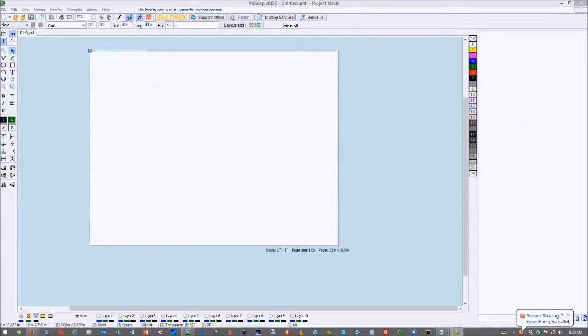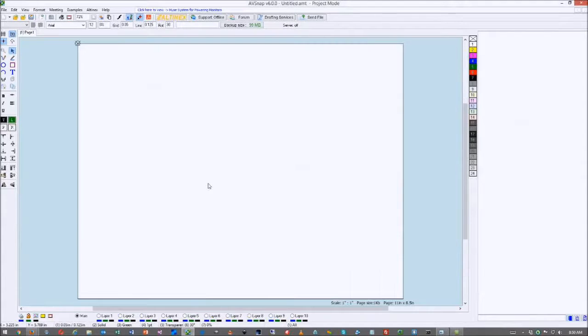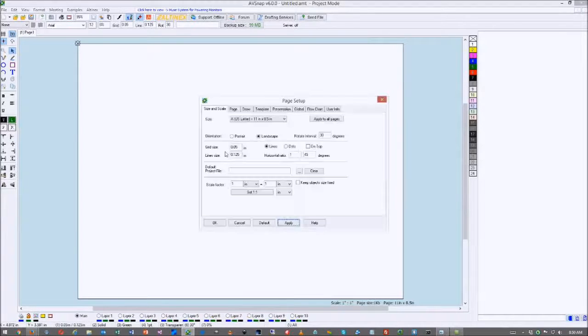But I do have a couple of questions in the chat, and one of the questions is about the plant picture JPEG. Yes, the plant picture JPEG, this will accept any type of bitmap. It could be JPEG, PNG, whatever you can put, or bitmap. Once it's moved on the page, we convert everything to JPEG. So double-click here and double-click on the page, or press the letter P as a shortcut for the page.